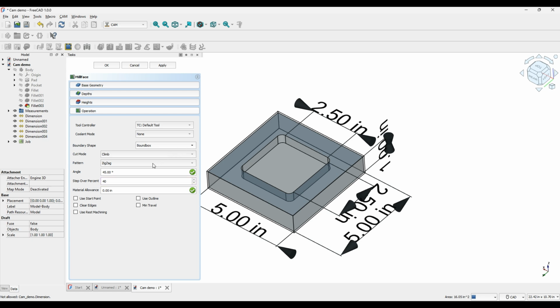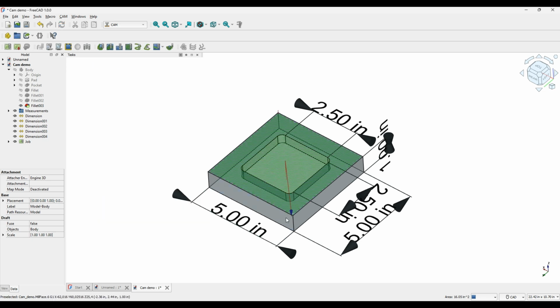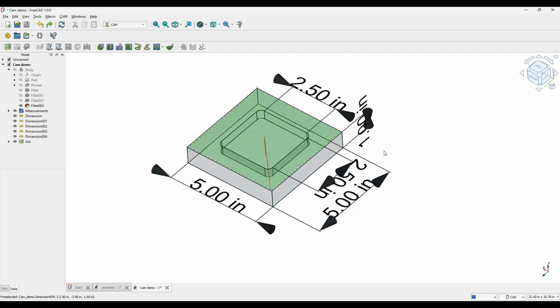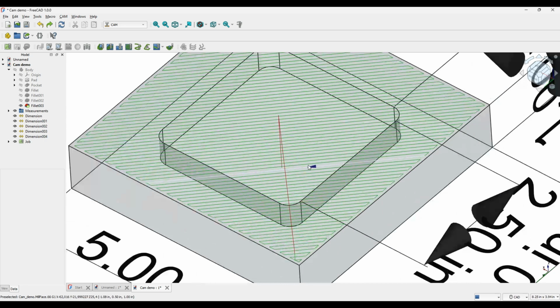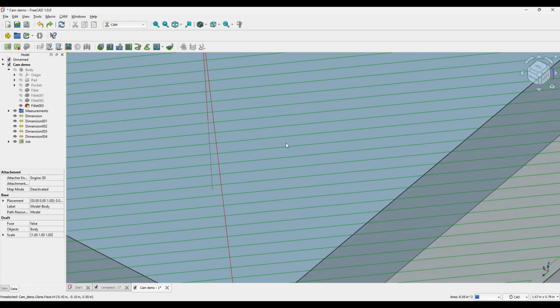So I'm going to tell it to stop according to the stock. Because if you look here, you're going to see these extra lines that exist outside of the surface of our shape. Those extra lines signify the 0.040 extra stock. So now we're saying to the cutter, make sure you get that. There still might be leftovers, but that's going to be the stop zone. Okay, so we've got that. And now we're going to click OK. So right here, you're going to see that's your cutter path. We've got that surface finished. We're going to switch gears and go down and activate that bottom level like so.